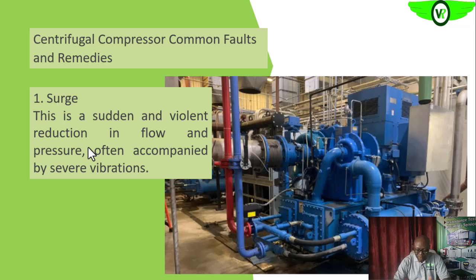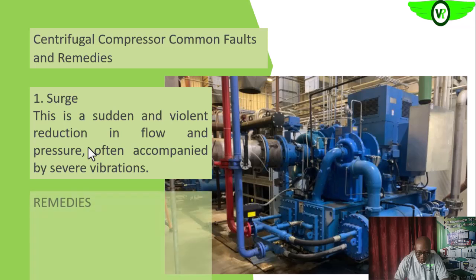So surge, like we said, is like a reverse pressure, okay, that is acting against the normal pressure within the compressor, and in most cases it's as a result of maybe the compressor not discharging properly. So if that happens, you'll see that we'll have a lot of compressed gas in that discharge area that will force itself back into the compressor.